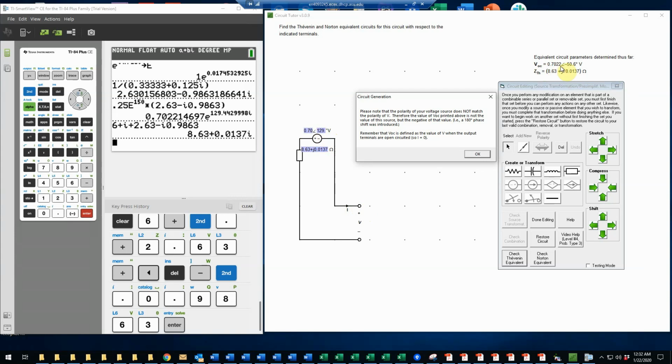So when it's printed VOC up here for me, as you may notice, the phase angle has changed. That's because it's subtracted 180 degrees from this value. And that's basically because multiplying by -1 to change the polarity is the same as multiplying by one angle 180 degrees, because that's the polar form of -1. Remember, in the Argand diagram, the -1 would be over on the left, directly to the left of the origin. So it would be an angle of 180 degrees.